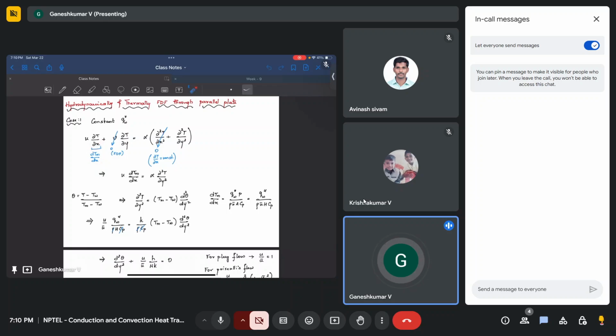For fully developed flow, based on the continuity equation, we have V equal to 0. And for constant heat flux, we know that dou T by dou x is constant, so the derivative of this is going to be 0. This can also be simplified, and you will end up with a simplified energy conservation equation. If you solve this, you will get the temperature profile.